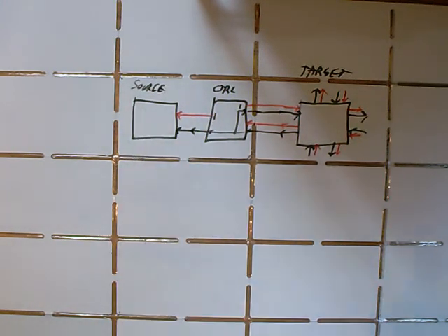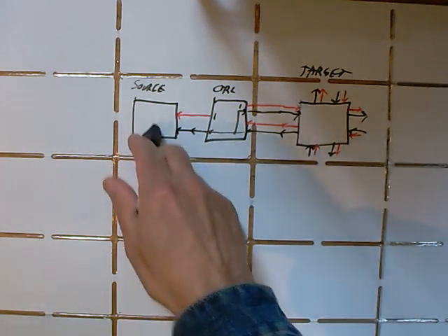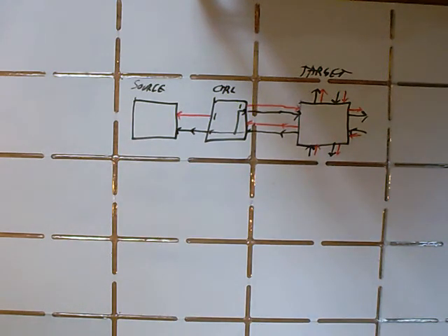And since it's asserting 1 on the source cell's C input, this cell's truth table is now being replicated into the source cell. In the case of 4-sided cells, there's 128 bits in the truth table. It takes 128 clock ticks to read all the bits of this cell's truth table, and after 128 clock ticks, this cell will be an exact clone of that cell. So whatever function this cell was set up to perform, this cell has now been configured to perform the same function. So this is a non-destructive cell replication operation.